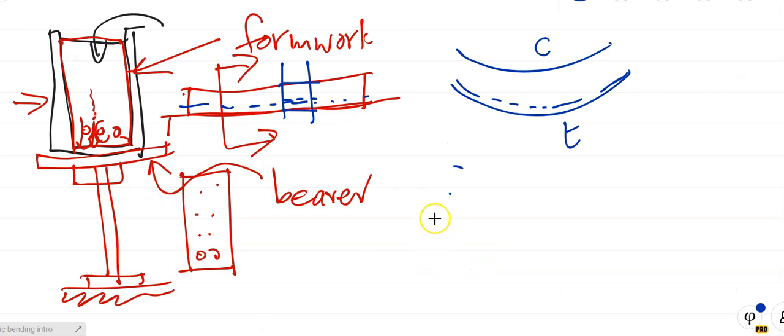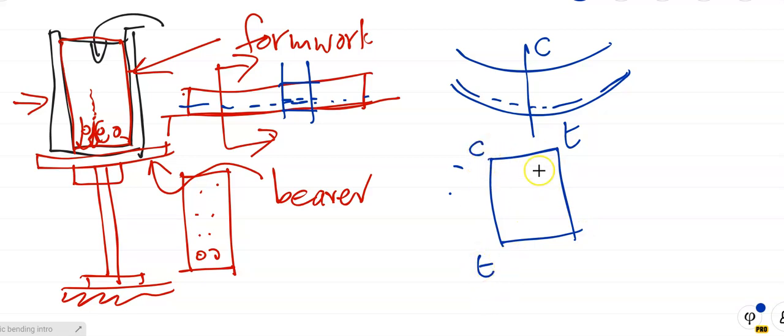Okay, so that's what we're talking about there. And the neutral axis. Now, why is there a neutral axis? If I take a cut along the beam there, my beam looks like this. The fibers at the top are in compression, the fibers at the bottom are in tension. If I take a slice at the top there, the fibers are in maximum compression. If I take a sliver of the fibers at the bottom there, they're in maximum tension. If I take a little cut of the fibers just a little bit below the top, they're in compression but slightly less. And if I take another cut along there, they're in compression but even slightly less. If I take a cut along the bottom there, they are in tension but slightly less than at the bottom. If I take another cut over there, they are in tension but slightly less than over there. So what's going to happen? The tension gets less.